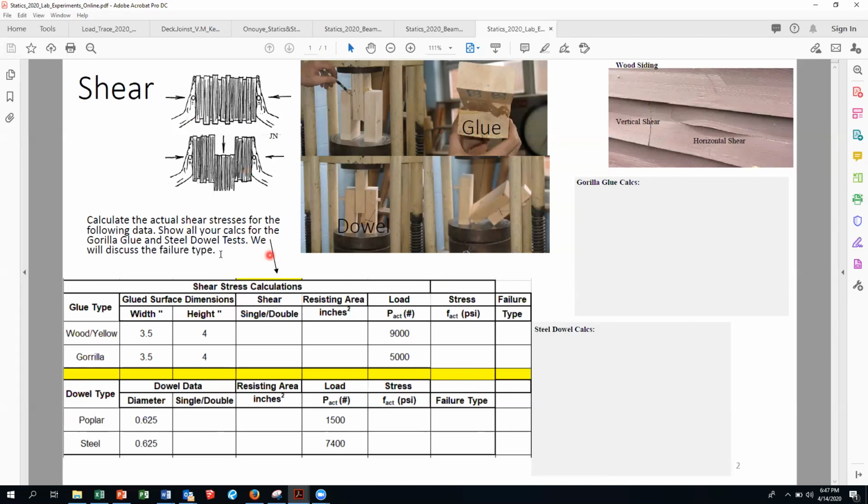So this, first of all, look at this. For this shear, this is vertical shear. This is critical. The formula for vertical shear is just load over area, load over cross-sectional area. Horizontal shear is 3/2 times shear divided by area.